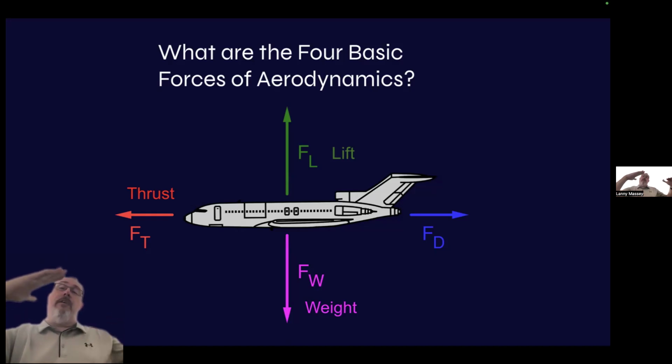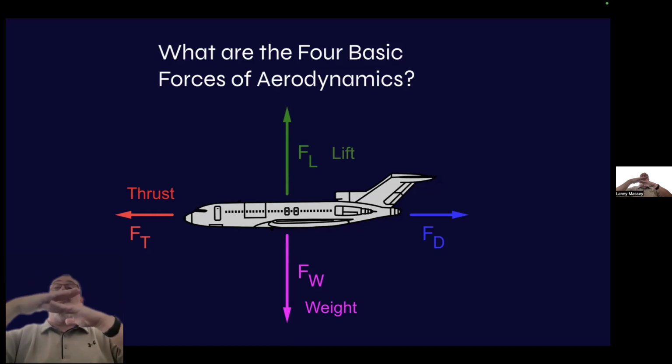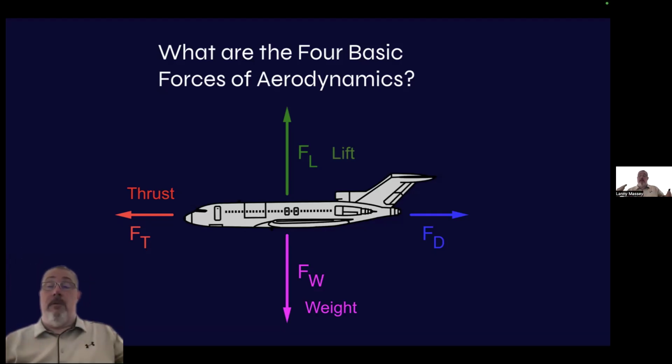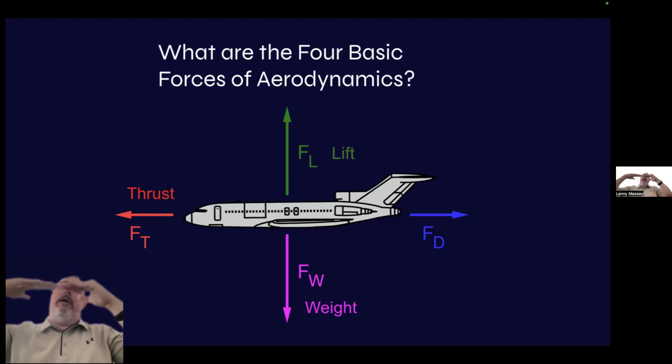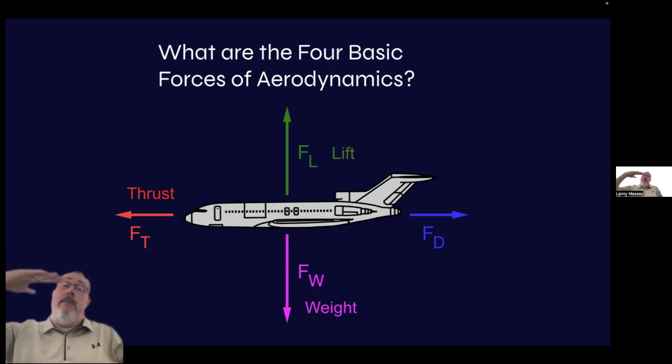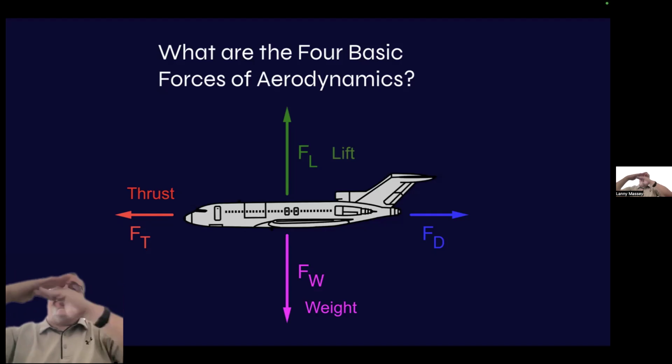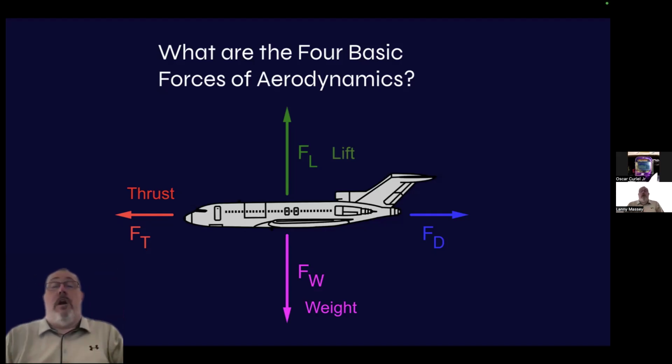In this case, you're not using Bernoulli's principle as much as just the plain fact that the air, and especially the faster you go, is going to push on that angle and force the airplane up. It's not a great amount of force because, like you said, it has to do with more area being pushed on with more force. By tipping it up, we have a greater area exposed to that greater force, which causes more lift. That's a perfect example of that.